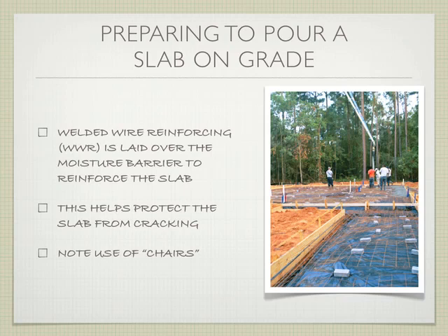So anyway, we'll talk about this in more detail down the road when we get to that part of it. But the point is, slabs in the state of California are getting more advanced than something this simple. So this reinforcing would work great in the Midwest, where you don't have earthquakes and you don't have the forces that we have to deal with. Today we're going to use more of the post-tensioning in a slab to avoid things like this crack that runs right along here, and there's a crack over there, and a crack right below you. That kind of stuff happens on a traditional slab like this because of all the movement and the earthquakes and that sort of thing.